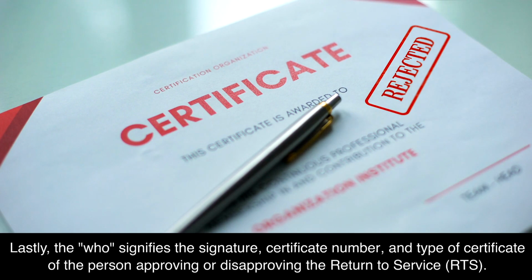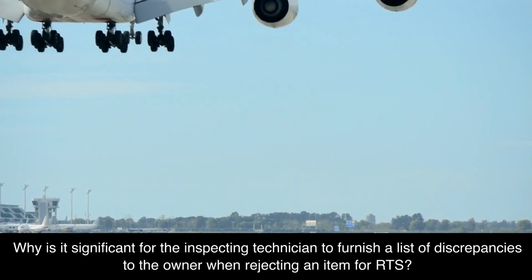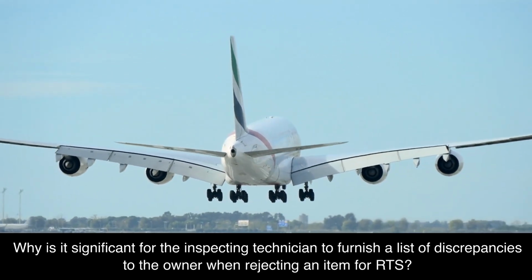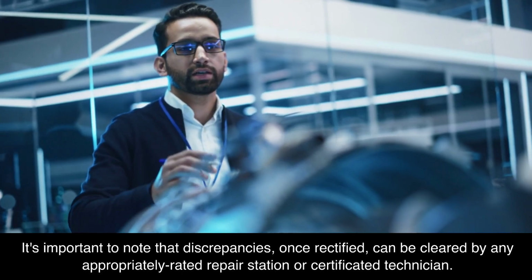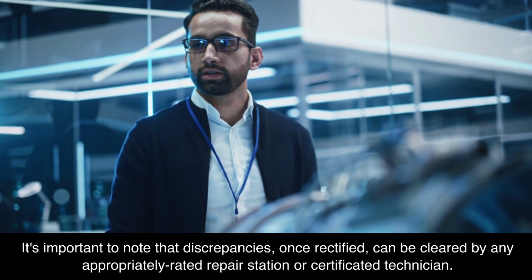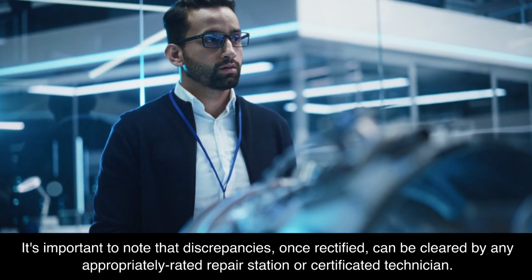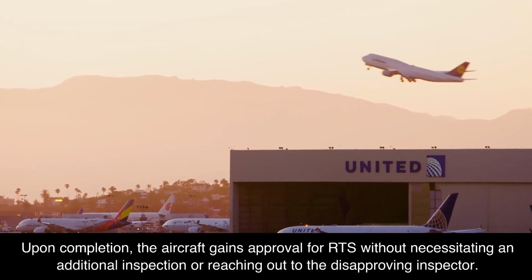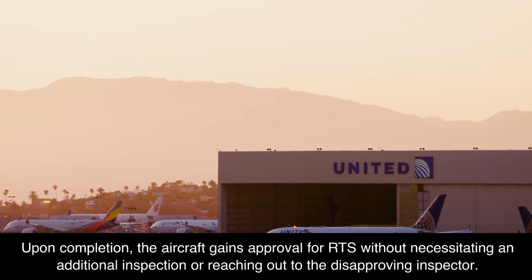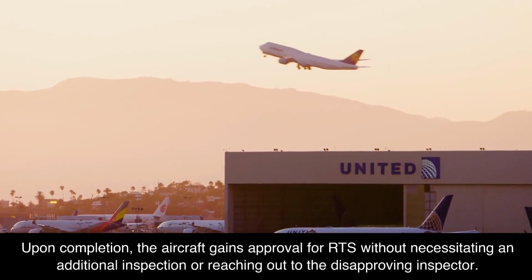Why is it significant for the inspecting technician to furnish a list of discrepancies to the owner when rejecting an item for RTS? It's important to note that discrepancies, once rectified, can be cleared by any appropriately rated repair station or certificated technician. Upon completion, the aircraft gains approval for RTS without necessitating an additional inspection or reaching out to the disapproving inspector.